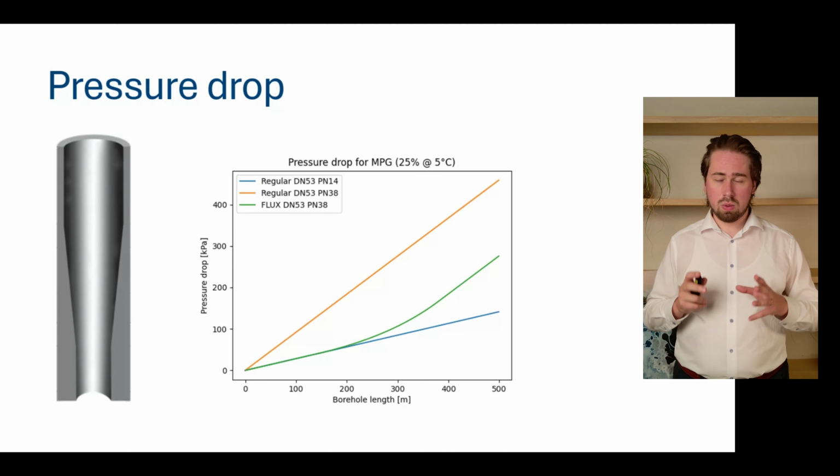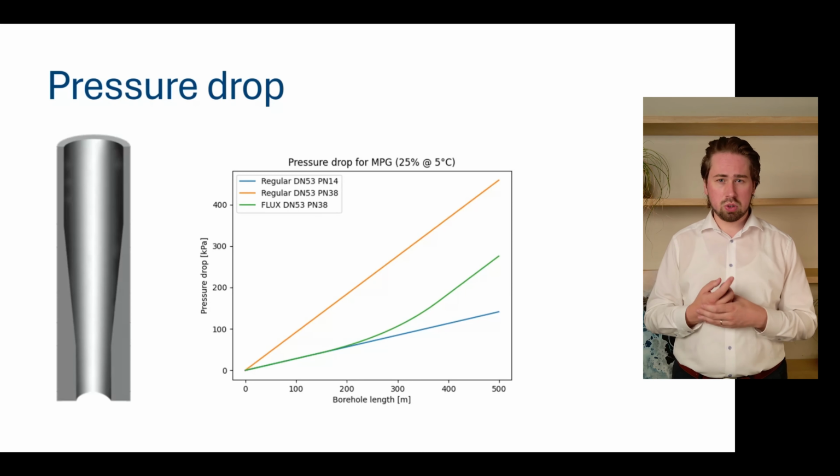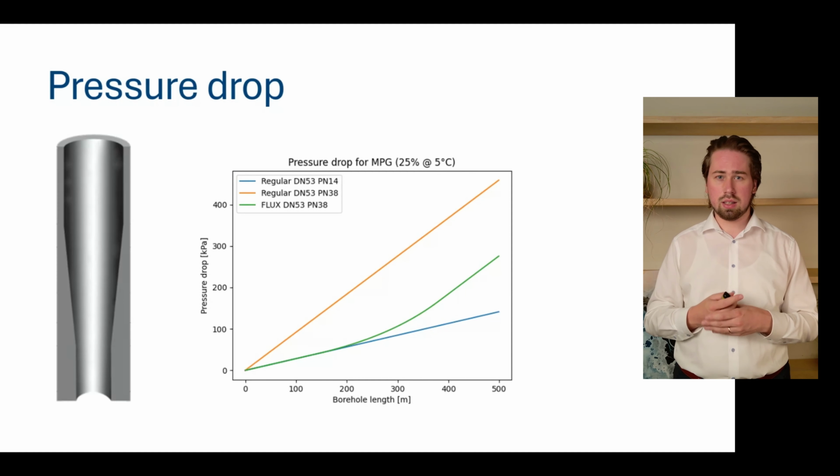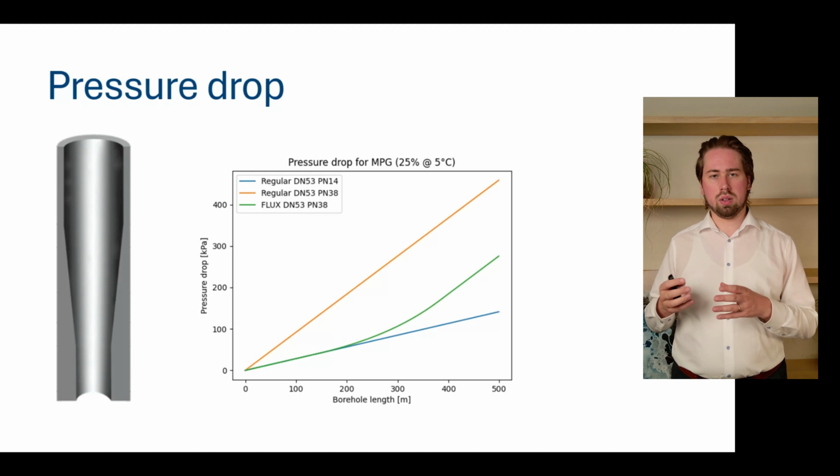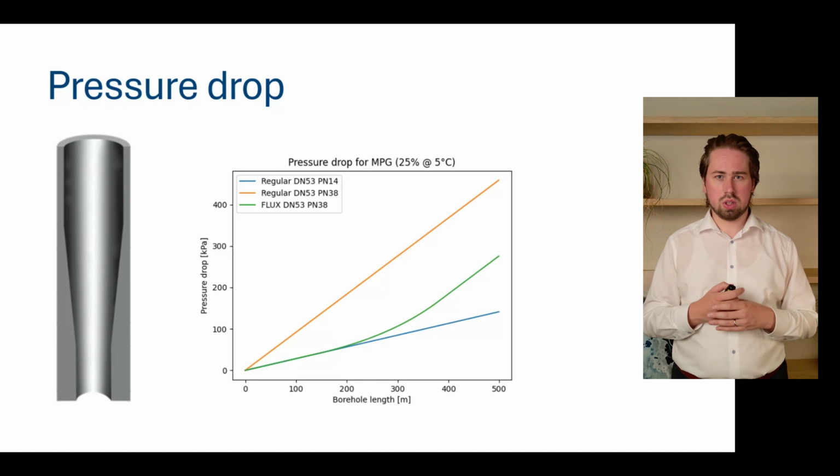So this was what I wanted to say about the GEROtherm VARIO and FLUX probes. I hope you found this interesting. Try it out in GHGTool for your perhaps deeper borehole projects and see how the pressure drop and the pump electricity consumption change when you go from a regular probe towards a conical one.